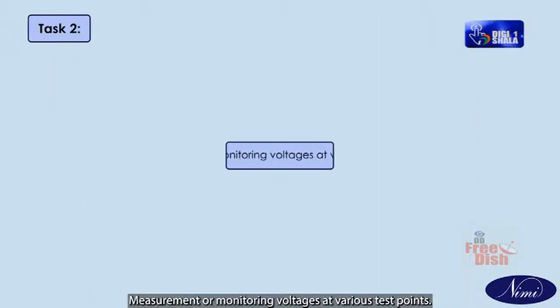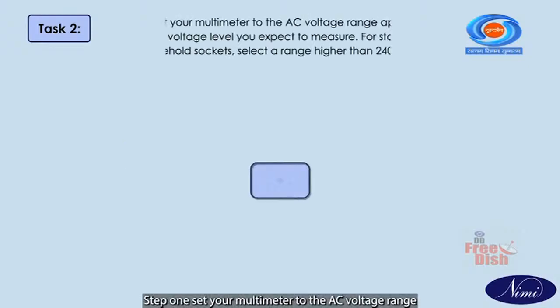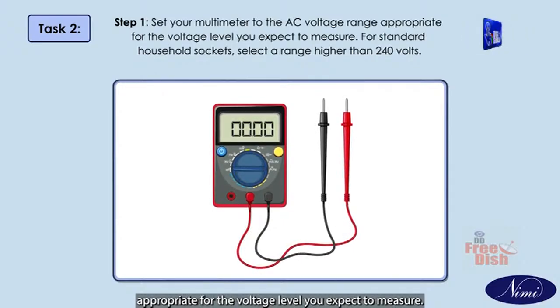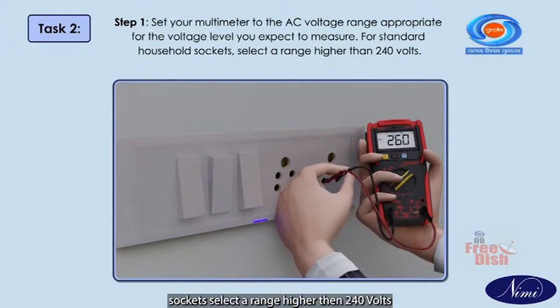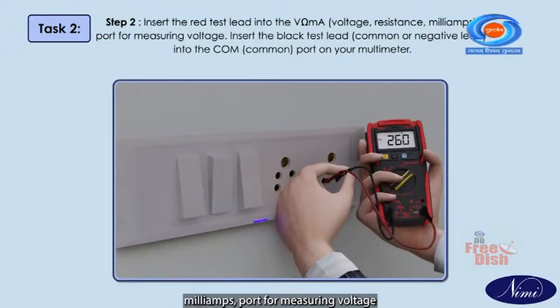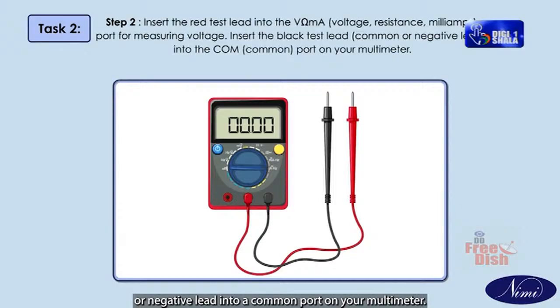Task 2. Measurement or monitoring of voltages at various test points. Step 1. Set your multimeter to the AC voltage range appropriate for the voltage level you expect to measure. For standard household sockets, select a range higher than 240 volts. Step 2. Insert the red test lead into the voltage, resistance, milliamps port for measuring voltage. Insert the black test lead, common or negative lead, into the common port on your multimeter.